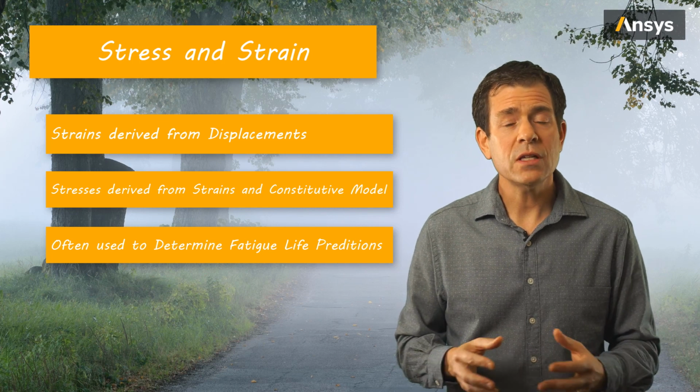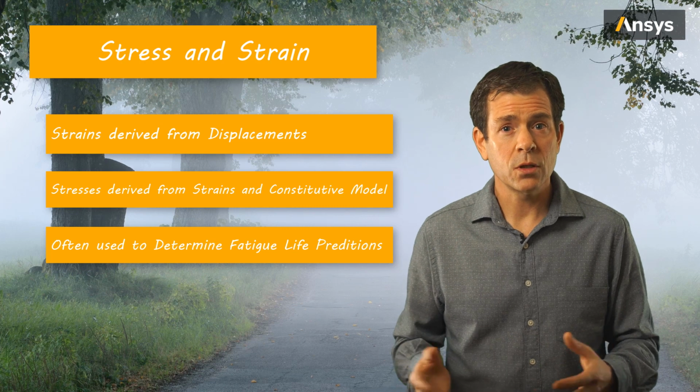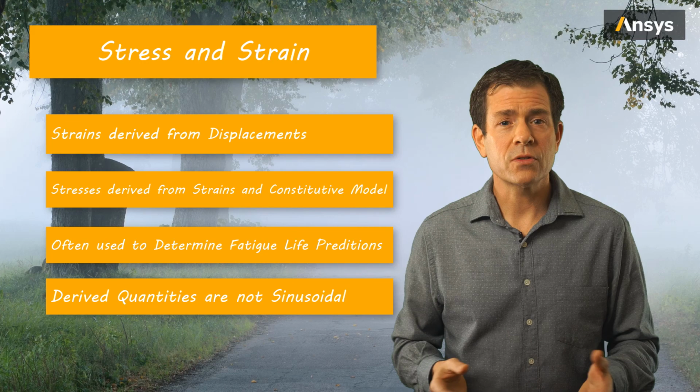Finally, while the stress and strain components, like the normal and the shears, are harmonic sinusoidal, popular derived quantities like principal stresses or equivalent stresses are not.